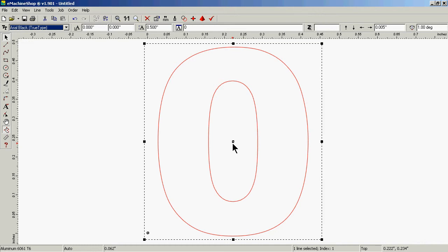So it's just something you'd have to play with, and before I would spend the time to engrave something as complicated as possibly that degree wheel, I would engrave some of these characters in the way that I'm going to use them on some scrap first and see how it actually looks and play with it first. Got to consider what it's going to look like machined.